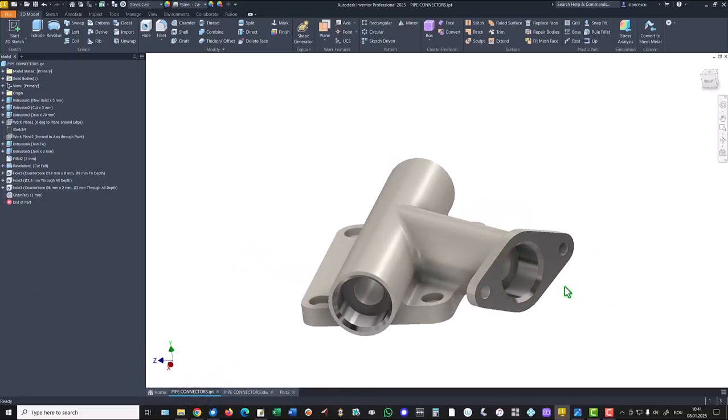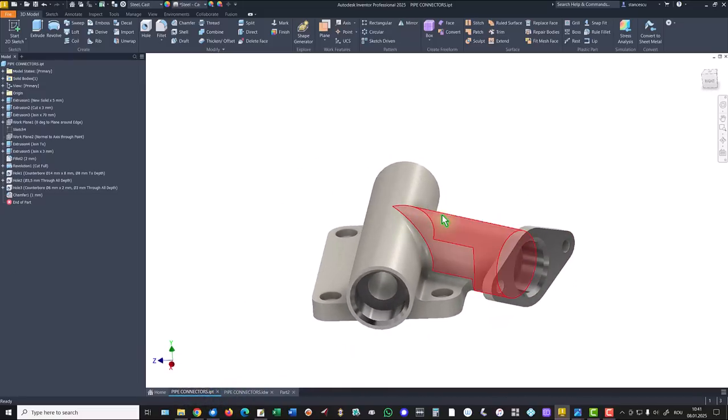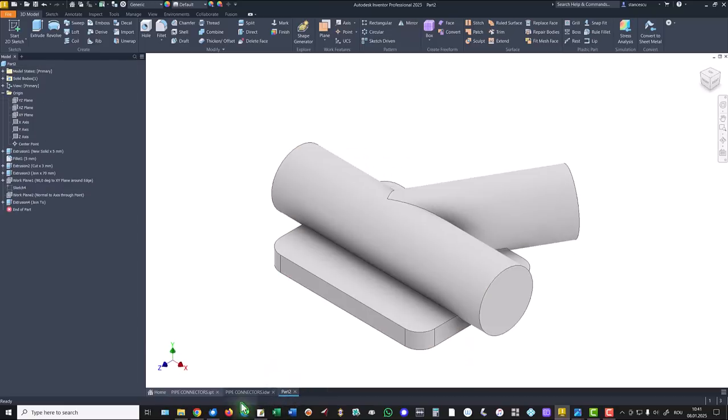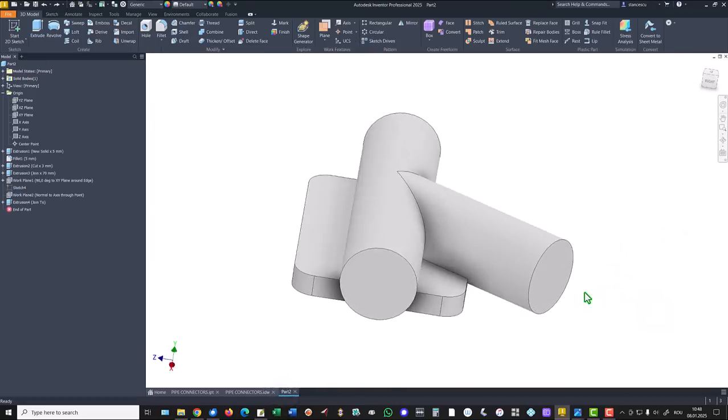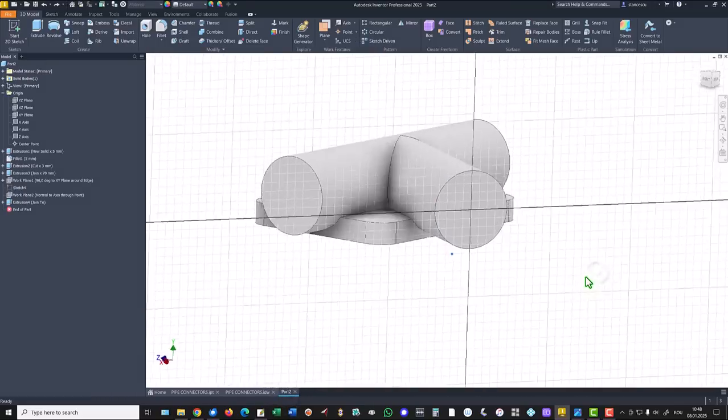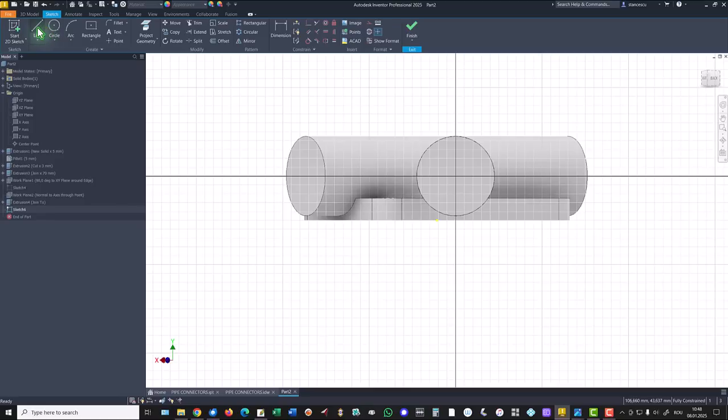Now the flange, this flange at the end of the last cylinder. Dimensions are here, 30 between these two centers, radius 4, radius 10.5, and the thickness is 3 millimeters. We select this face for a new sketch. Then we draw some lines.